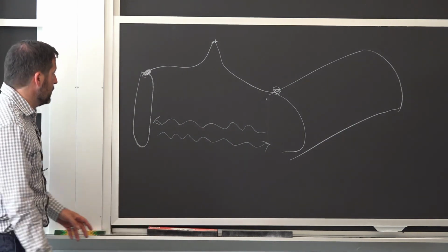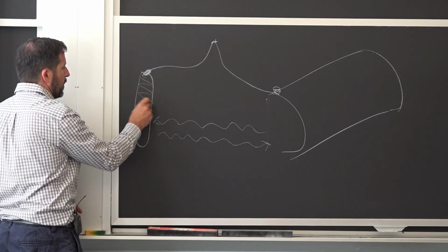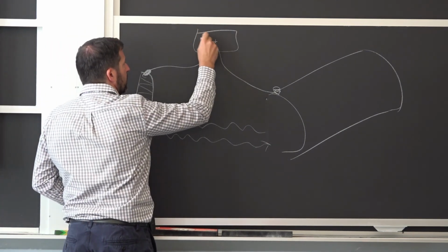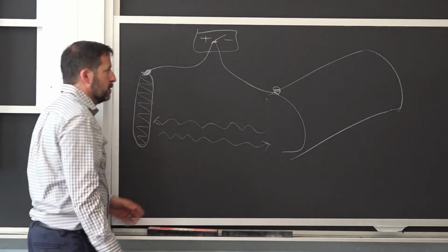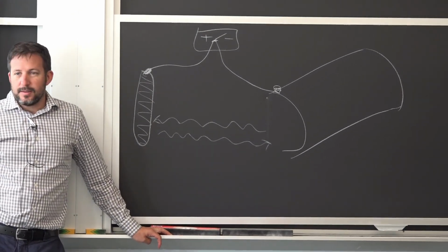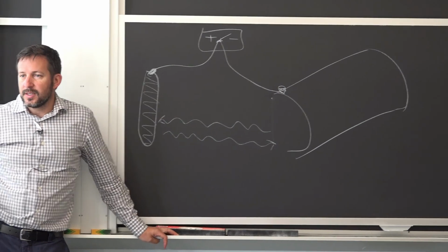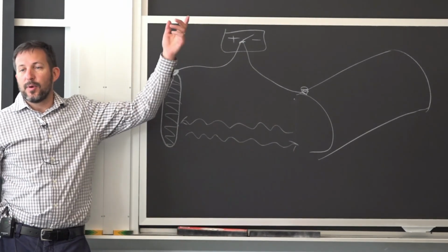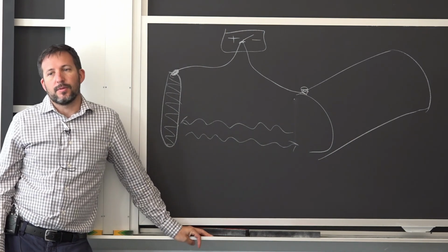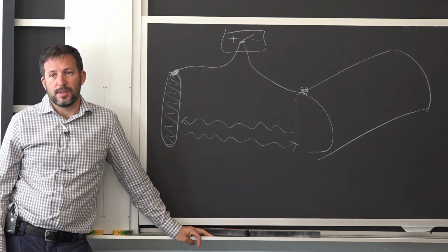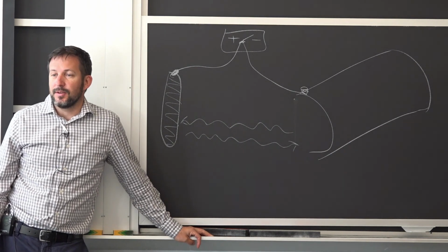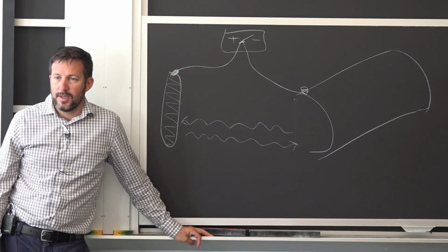The variation you can do, you can say this is going to be kind of a carbon anode, it's going to be a permanent anode, and then here you put your rectifier. That makes sense. And that's used for the oil and gas pipelines. That's super long term then. Yes, and it's not super expensive. It's mostly the setup to get the high power line to get you the power you need for every location that you put these. So the anodes, you don't have any necessity to bring electricity.